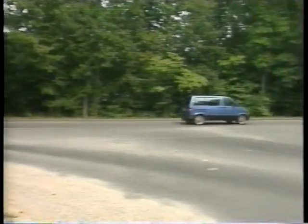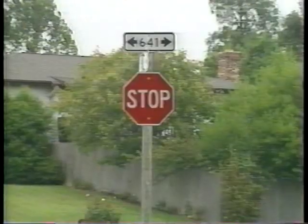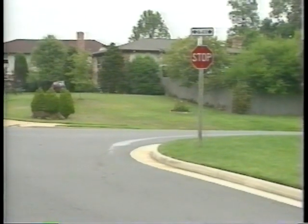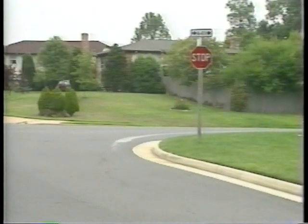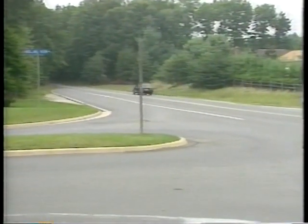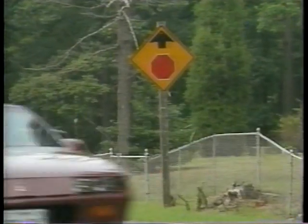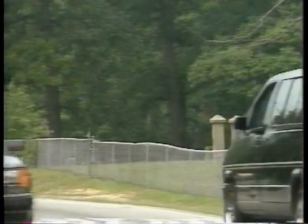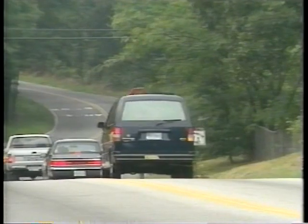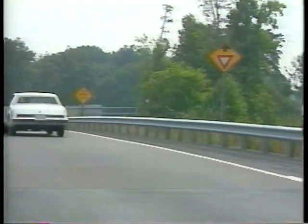In a rural setting, the concern is with intersections and non-intersections. The stop sign is used at the intersection of a minor road with a major road, when using a yield sign would be hazardous. At intersections, in addition to the stop sign, there may be a need for stop ahead signs. These signs are used when the stop sign cannot be seen from enough distance for the driver to stop safely. The yield ahead sign is used under similar circumstances.